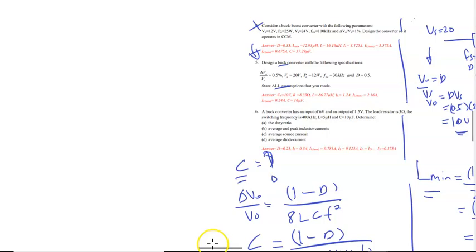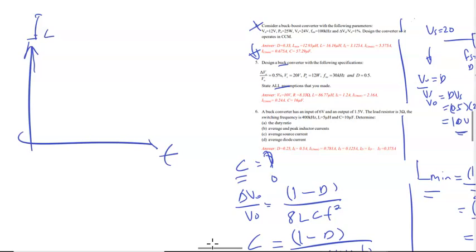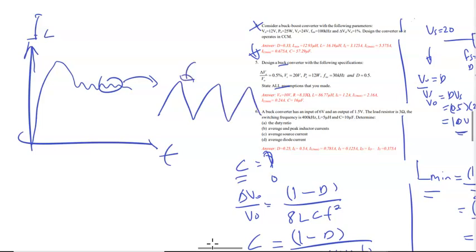Okay, so in terms of how much the current that flows inside your inductor, you can calculate, because you want to know the response in terms of your IL versus time. So when it starts, then it will have a ripple. If you zoom this area, it will show you how much in terms of your maximum and minimum. So this is your IL max. This is your IL minimum, and it should be above 0.